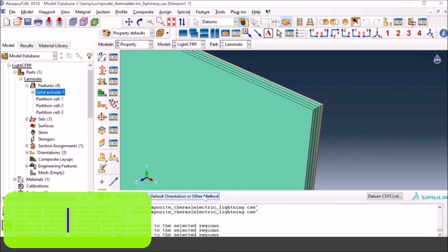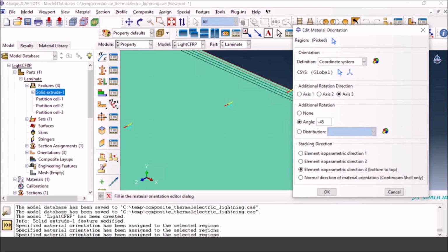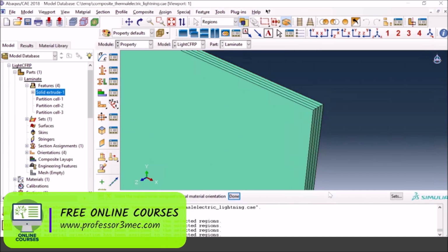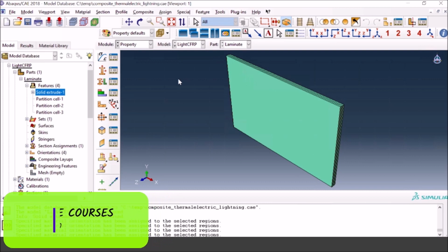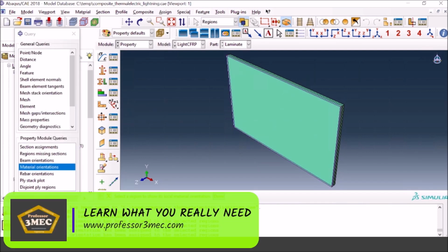So depending on the orientation, you will see later on how the temperature distribution also changes, which is also dependent on the orientation. So again, in this case, we will give, let's say, 90 degrees. Again, these are arbitrary. You can select whatever you want based on your own data. So I think properties are now correctly defined with orientations and also orthotropic with directional dependence as well.